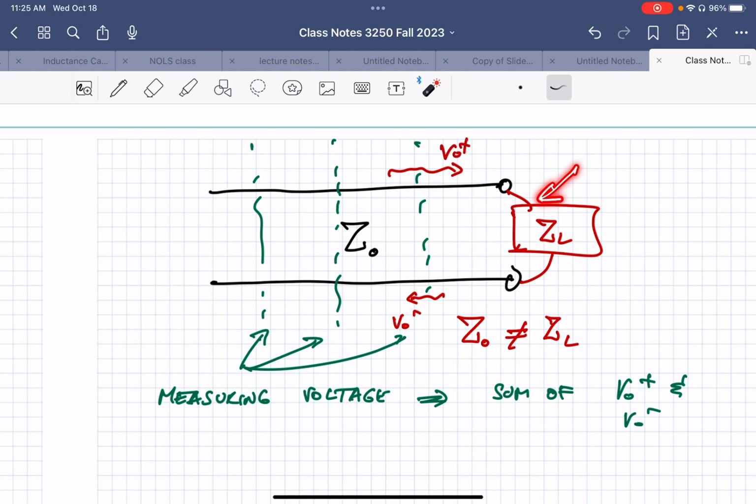It's not like you can put a multimeter across something and figure out what its impedance is, because multimeters are at very, very low frequencies, practically DC frequencies. So you can't use a multimeter, and that impedance also changes with frequency, and you're measuring it at multi-gigahertz. So in practice, you can't really measure the impedance directly, and people use this standing wave, the amplitude of the ratio of the sum of the voltages along the line to figure out something about the load.